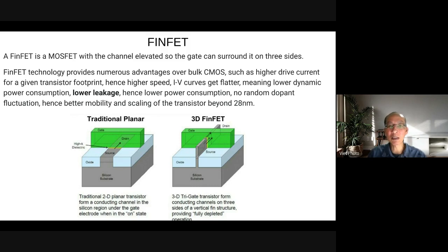And it also scales better, because you can see that the transistor is smaller, right? This one has a transistor only this size. This one needs to be larger because of the width here. Now the width depends on the vertical one here, not the horizontal one here, so it can be smaller. That's really what we wanted. So it's from 28 nanometer. They say 28, but actually I think it got into production at about 20 nanometer and up until now.